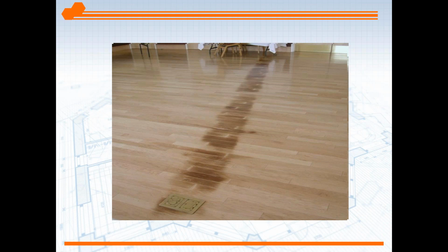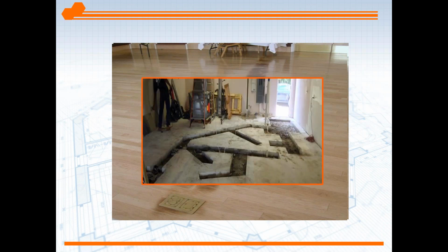The floor, prior to the wood being installed, was perfectly dry. Once they had trenching done and compromised the vapor barrier underneath, they had a problem for the life of that floor potentially. So if you're ever working over a floor that has extensive trenching or full depth patching, you may want to assume that the floor will no longer be dry.